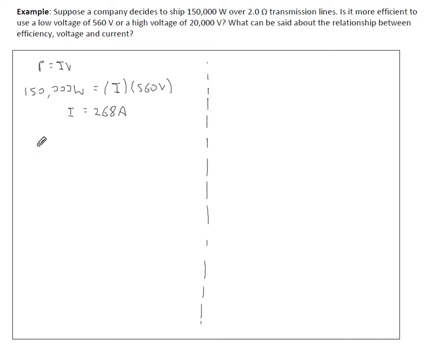So lost power, because that current is being traveled through this very long line from wherever our power station is, like the hydro dam, all the way to our homes or whichever other source of energy we're getting from. That current is passing through the wire. Normally we don't think of wires as resistors, but they are. The wires are using up or consuming energy.